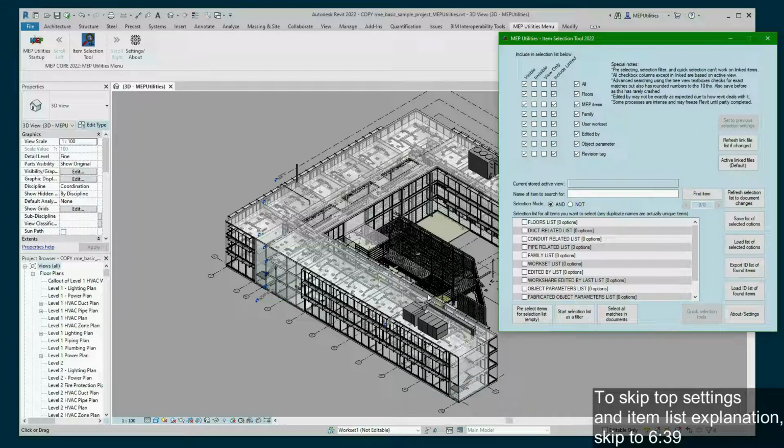You've got family items, which are different family elements, instances of family pieces. So like the pieces of duct, the lights, the different elbows and stuff to the duct, because those aren't Revit parts. And also fabricated items too, potentially. Actually, fabricated parts wouldn't be in there, but things like mechanical equipment would probably be in that list.